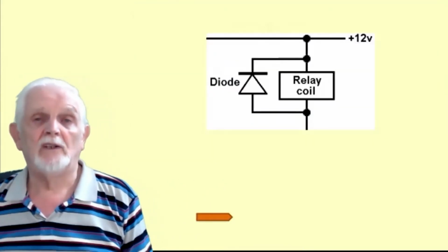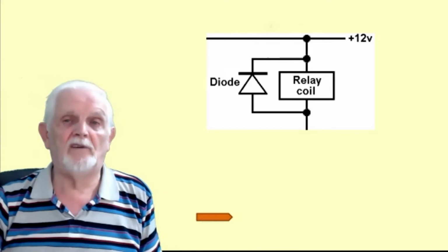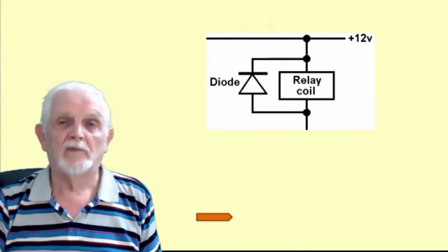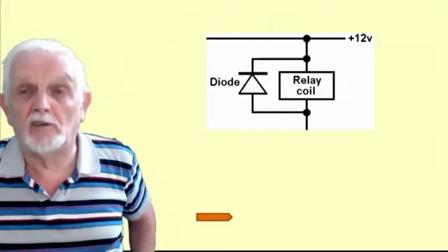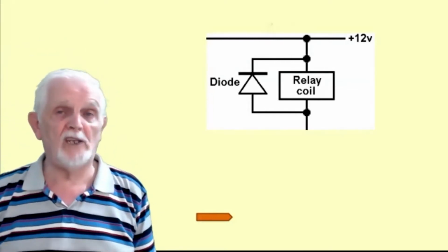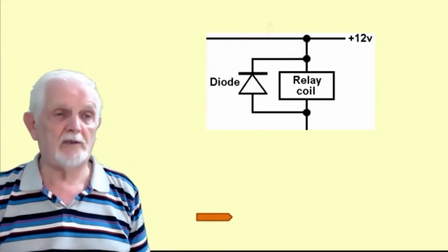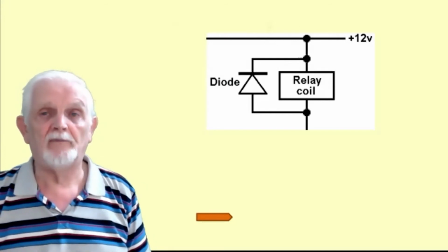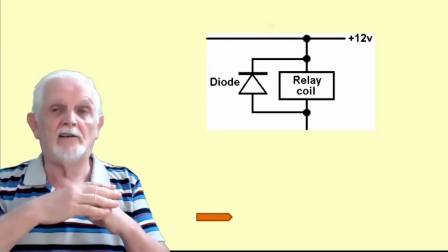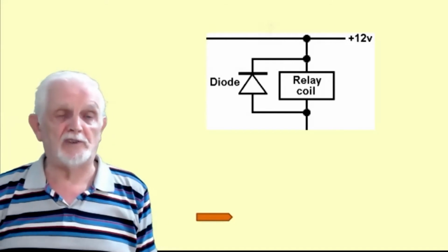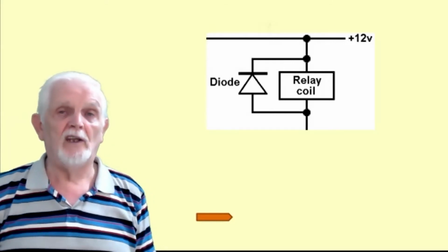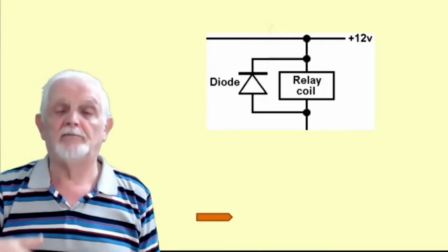If you want, you can replace the light with a relay. And right away, we've got ourselves a new animation. The train comes into a factory, goes over the LDR. The relay can switch a higher current device like a motor, and the conveyor belt starts running.